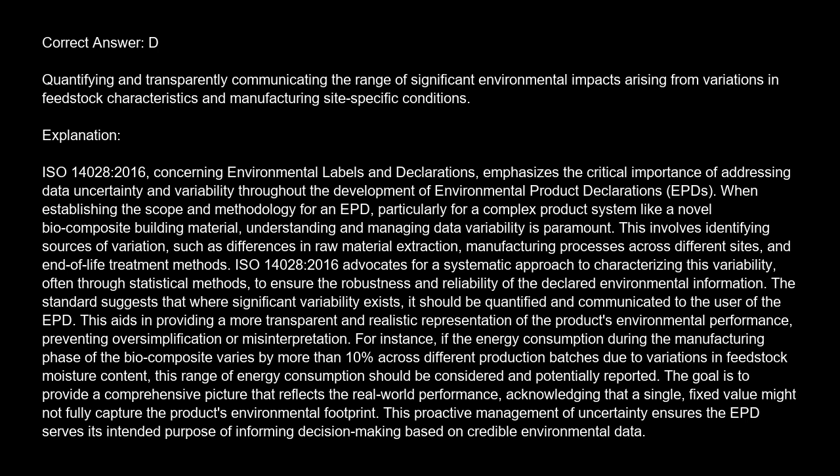For instance, if the energy consumption during the manufacturing phase of the biocomposite varies by more than 10% across different production batches due to variations in feedstock moisture content, this range of energy consumption should be considered and potentially reported. The goal is to provide a comprehensive picture that reflects the real-world performance, acknowledging that a single, fixed value might not fully capture the product's environmental footprint. This proactive management of uncertainty ensures the EPD serves its intended purpose of informing decision-making based on credible environmental data.